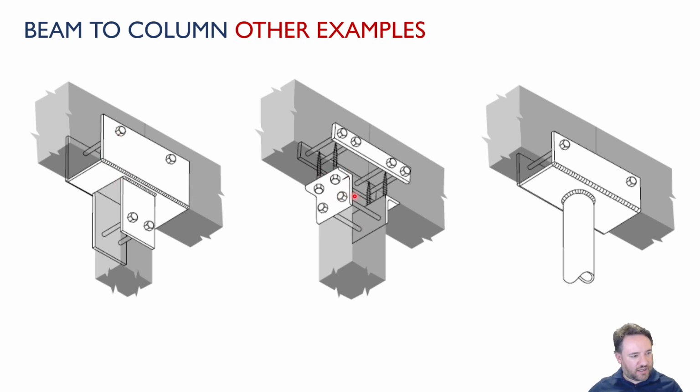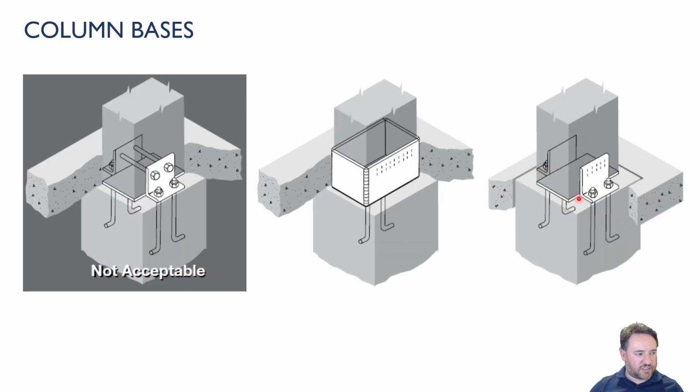Here is a clip angle connection. So basically I'm providing support for the bottom using this angle, some bolts here, and these are lag screws, and then keeping these from moving relative to each other longitudinally using single plates on either side. And this is a full up welded up connection where I have a steel column instead of a timber column. I'm just using a manufactured connection to keep everything together.